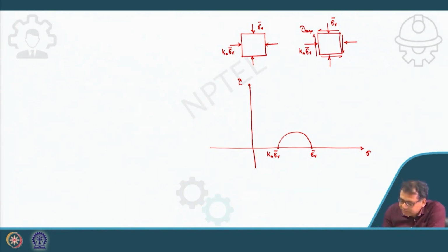Now if I extend this, the point on the Mohr circle under the second stage will be on this line, because the coordinate for the x axis, the vertical normal stress axis, remains the same as the first stage, but a tau max is added.